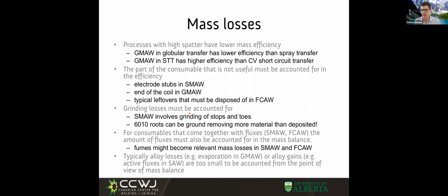And there are companies that throw away boxes of stick electrodes, probably 7018, which are low hydrogen electrodes. If you put them in the furnace, you can get the moisture away. There are many parameters for how long and at what temperature you should do that. The Lincoln Procedure Handbook has a section on how to recover electrodes that have been exposed to moisture. But very often it's just faster to trash it and open a new box, right? And time is money. But when we are so inefficient, we might end up paying a price for that, right?